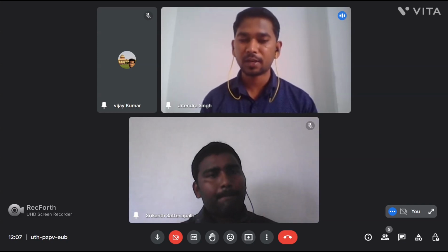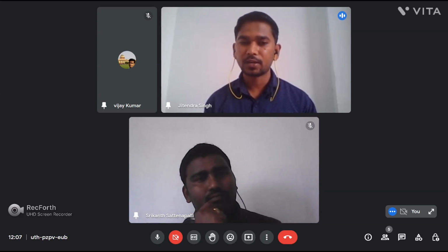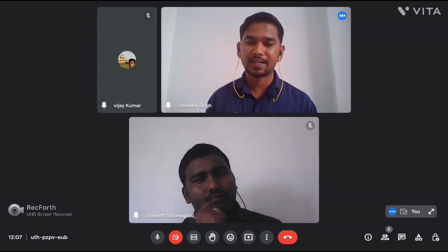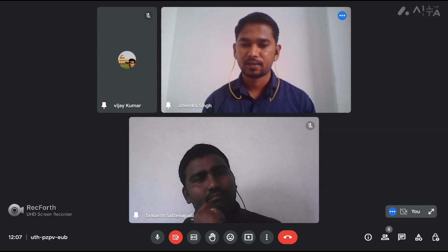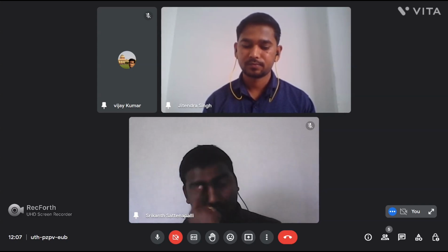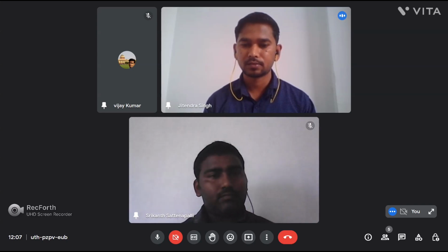Hi, Jitendra, tell me your question. Yeah, sir. The advantage of SPI is that it has full duplex, so master and slave can read or write at the same time. And one disadvantage is that if we increase the slave connections, then the slave select lines increase, so the circuitry also increases. That is the disadvantage over I2C. Okay, got it. You can add some more points also. No problem.